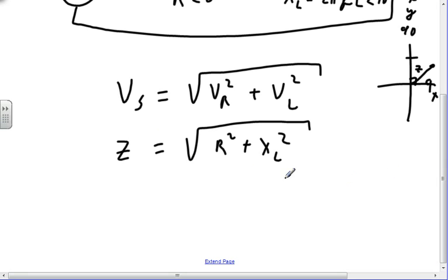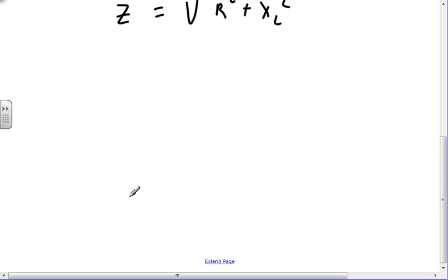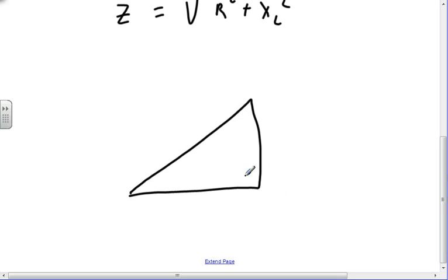So, but I'm looking at it as a Pythagorean Theorem thing. If I have a right triangle, A, B, C, then C squared is equal to A squared plus B squared, given to us by the Greeks 2,500 years ago. The Greeks didn't know about electricity 2,500 years ago, but the Pythagorean theorem that they left us applies to a resistive inductive circuit.